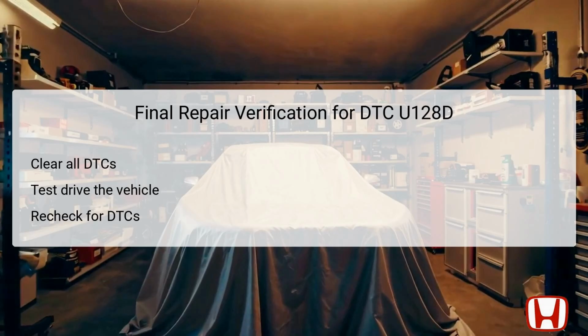Once all troubleshooting and repairs are completed, it's imperative to verify the fix by clearing all diagnostic trouble codes in the vehicle system using the HDS. This action resets the ECU, electronic control unit, and allows it to function without historical errors impacting its performance. Following that, a test drive of the vehicle is crucial to confirm the repairs were effective. While driving, monitor the HVAC controls and gauge readings for any further irregularities. Performing this step ensures that everything is functioning as intended under actual driving conditions.